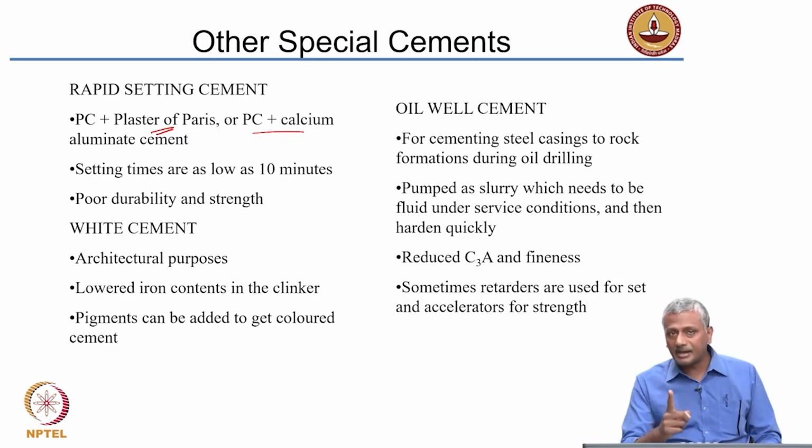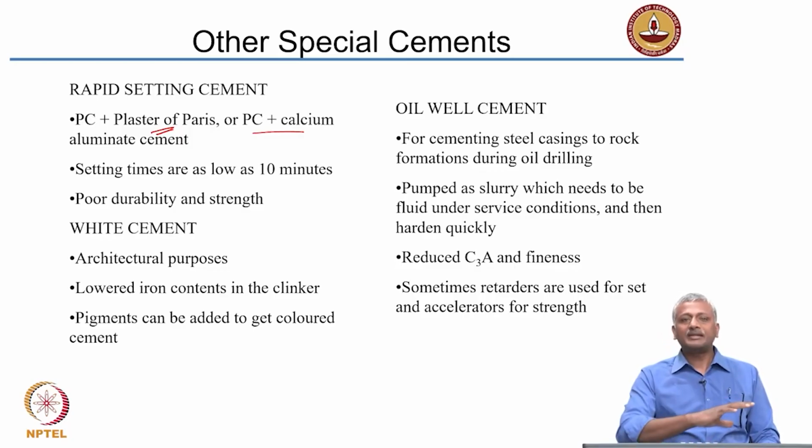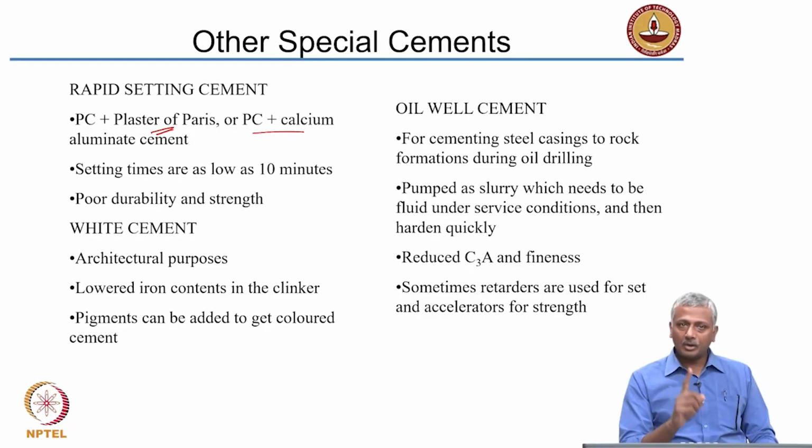It is not rapid hardening cement. We talked earlier about rapid hardening cement or high early strength cement. Those cements are formulated to develop strength at an early age, but they are not necessarily rapid setting. They set normally, but they can get strength at an early age. Here we are talking about rapid setting.